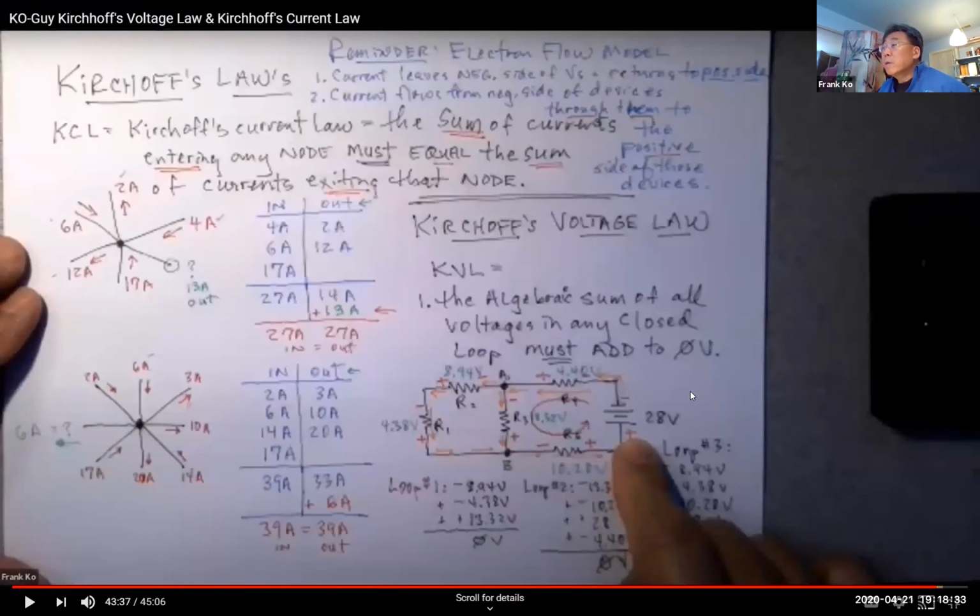almost to the end. Let's see what we can see here. All right. This is good because we have these voltages and we have these polarities based on the previous YouTube, but how do we know any of these are right? How do we apply Kirchhoff's voltage law? So for Kirchhoff's voltage law, loop 1, is this a loop right here? See this little square on the left? That is called a loop.